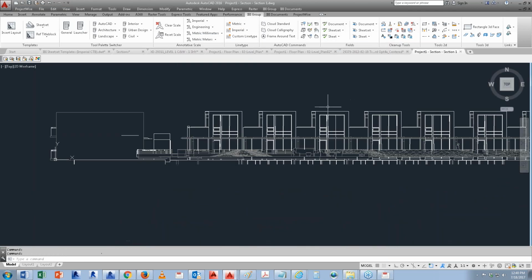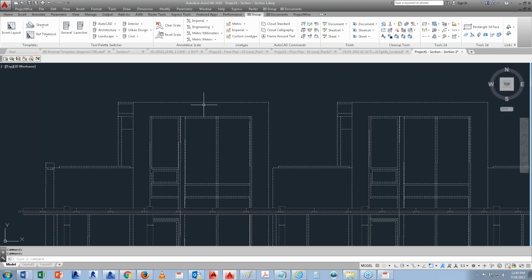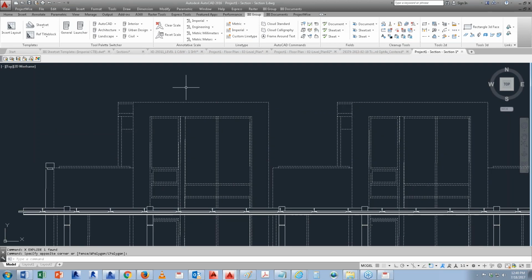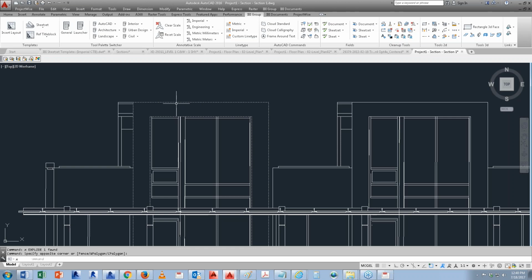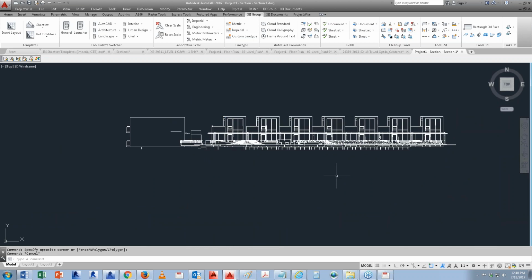There you go. So that's basically just a CAD drawing. So you could just keep exploding until you get a bunch of lines. Okay. Save you lots of time. So I'm just going to explode again. You see that's just a bunch of lines. Okay. So you could just translate a lot of your SketchUp model into 2D lines, so that you don't have to show everything in 3D.